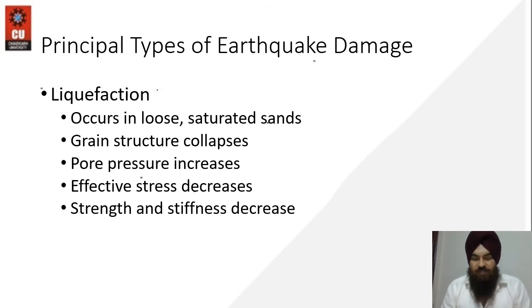So liquefaction is basically a combined phenomenon involving a combination of loose soil, that is cohesionless sand. The soil should be cohesionless or loose in nature, and it should also be saturated. Then when earthquake waves of a certain frequency arrive, they lead to the collapse of the grain structure. This is the whole phenomenon of liquefaction, in which the soil beneath the structure turns into fluid for a fraction of a second.